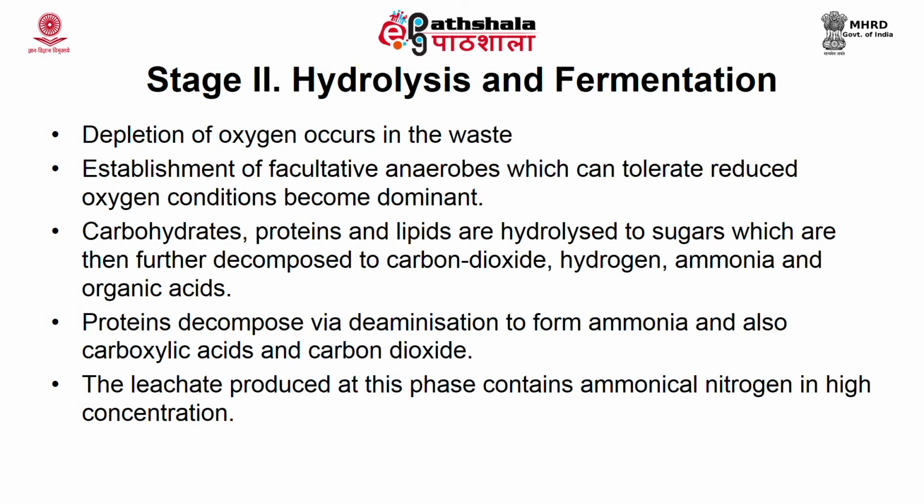So, the left out carbohydrate, proteins and lipids which were not hydrolyzed or degraded in stage 1 will be hydrolyzed to sugars in this stage, and will be slowly decomposed to hydrogen, ammonia and other organic acids. The proteins will decompose to ammonia, carboxylic acid and carbon dioxide. So, since there is degradation of protein, that too in anaerobic condition, you can find a lot of ammonia generation during this phase. If you analyze the leachate at this stage, the ammoniacal nitrogen will be very high.